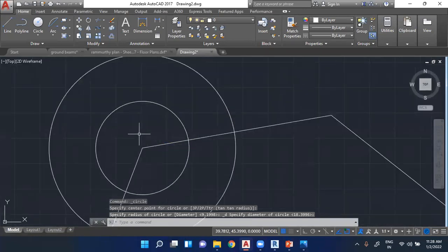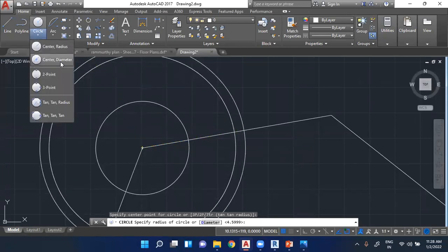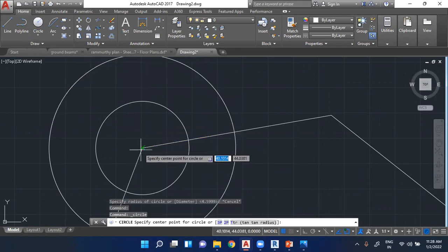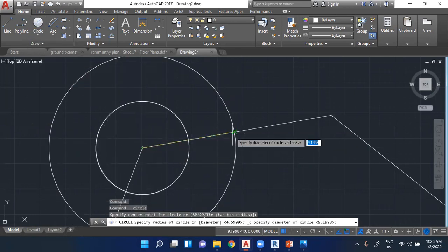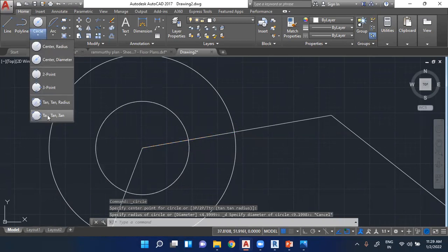What I'm telling AutoCAD by this is to plot me a circle. The length I'm putting is the radius, and it'll take that length as a radius and plot me a circle. And when I'm checking the diameter one, what I'm telling is that the length I'm specifying here is the diameter, and the circle needs to get that diameter, and it'll take half of that length and plot me a circle here. Likewise, there are many other options that need to be checked here.